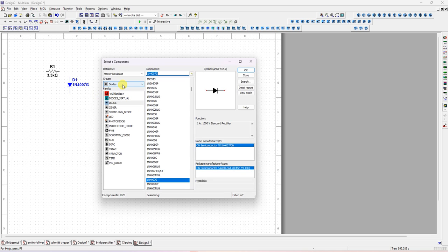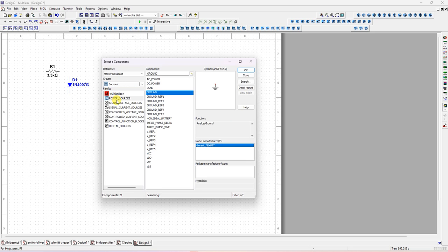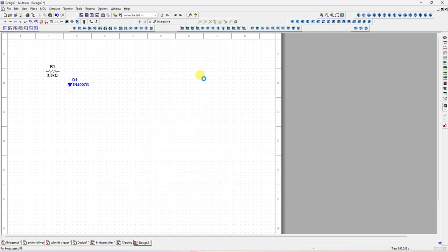I want a reference voltage. So that is there in the group. You have to go to sources group. In the source group, click on power sources. Above in that power sources, right side, AC power is there, DC power is there. I am selecting DC power. Click OK.